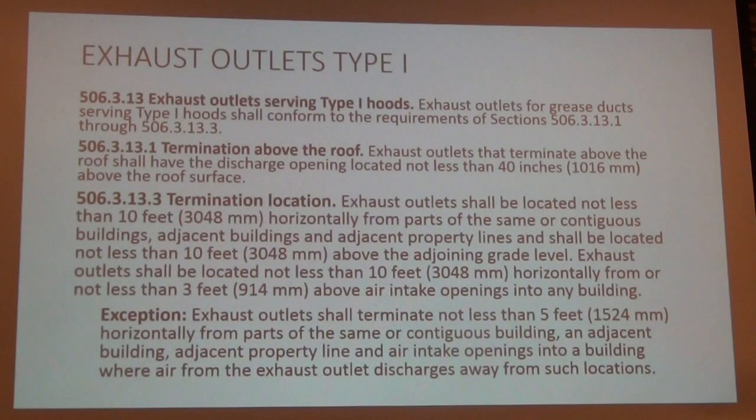How about adjacent buildings? If there's an adjacent building, there would be a concern. Isn't that an adjacent building next to it, though it's on the roof? Yes. So whether the strip mall is one property or not, it's still saying adjacent buildings, because you don't know if they're going to build that up. That's why I think it's there, because we've had situations where they built a roof up, and there was an exhaust fan right there. So when they build the wall up, they created the violation, then you would write it up then, and until then you'd leave it alone. There's a saying in ICC: you can't write something up on the pretense that something might happen down the road.